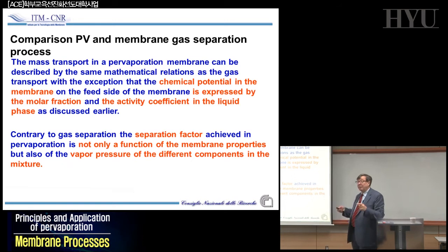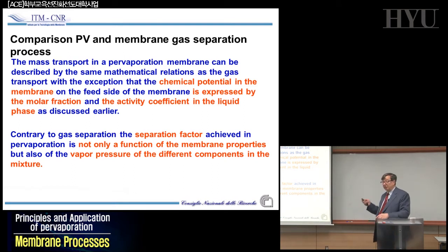But if at one point, for a certain level of concentration, the concentration in the gas phase is equal to the one in the liquid phase, when you condense, you have the same composition. So you cannot separate anymore. This is called azeotrope.